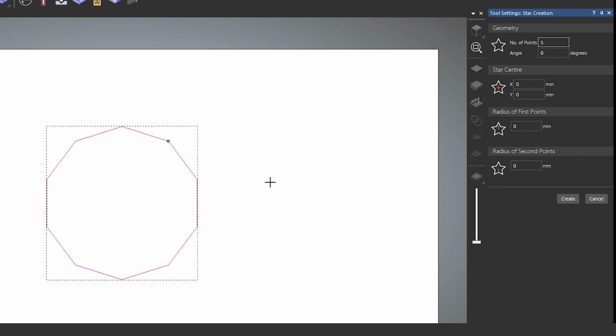And if we try to draw it manually, we'll see what happens. The first time we click and drag, we will get the 5-side pentagon. This is the outer radius, or the first point radius it is called in the menu. Once we release the mouse, we will then get the option to do the second radius or the inner radius. Obviously it can technically be an outer radius as well if you go in that way, but usually you will do it as an inner radius. And as you will see as I'm pulling this in and out, the figures on the right hand side also adjust accordingly.